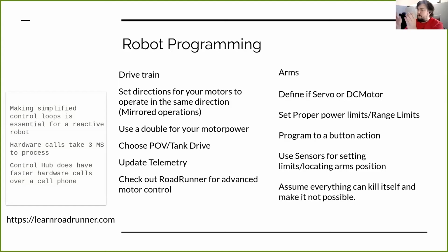Or if you have color sensors on the arm designed to do different things: this is the distance measuring color sensor, this is our object detecting color sensor, right? Have those match different things. Have it be clear so that as those go and read different values and come back, you can easily modify and work with that. And putting labels on them, a little bit of white gaffer's tape and some Sharpie can go a long way for keeping your sensors straightforward when you label them after your A/B testing, and keeping them straight on the robot.